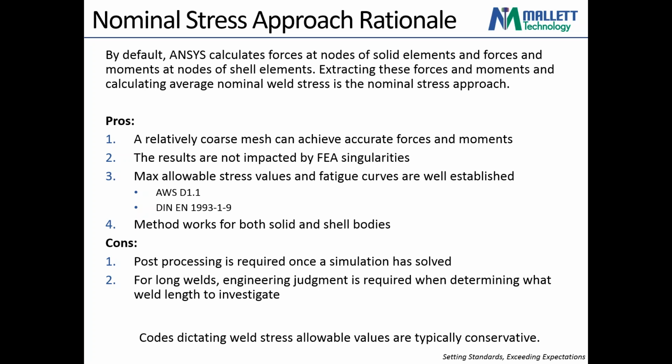The second con is if we're looking at a long weld, some engineering judgment is required, because generally what you're doing with the nominal stress approach is defining the worst-case section of a weld that you want to extract the forces from.